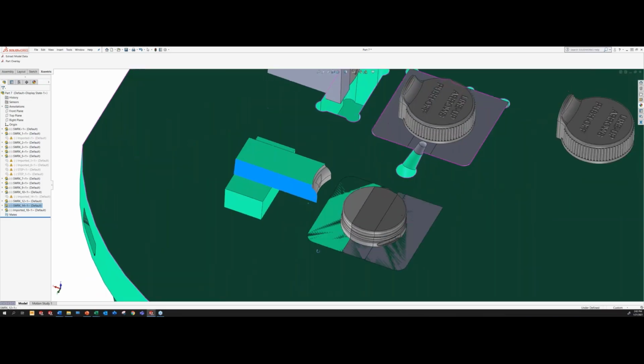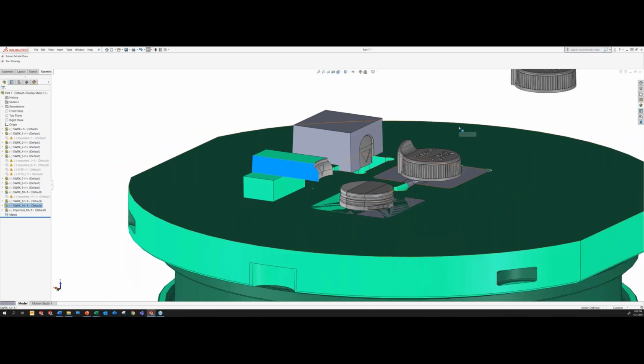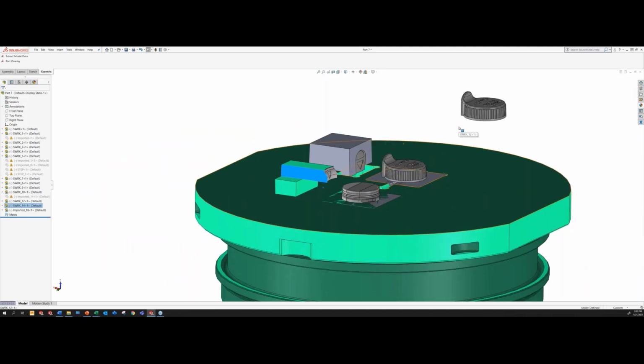All right, guys, our last question is with regard to sizing that Eccentric is capable of doing. Does Eccentric have any experience with large parts, 1 meter by 1 meter with low wall thicknesses, like 1.4 mil? Not that big. Our biggest footprint that we can run internally here is roughly 24 inch by 24 inch with a 5 inch depth, or like a 28 ounce shot size. We have partners here locally in Michigan that we can use and have used for bigger tools, but nothing that big.